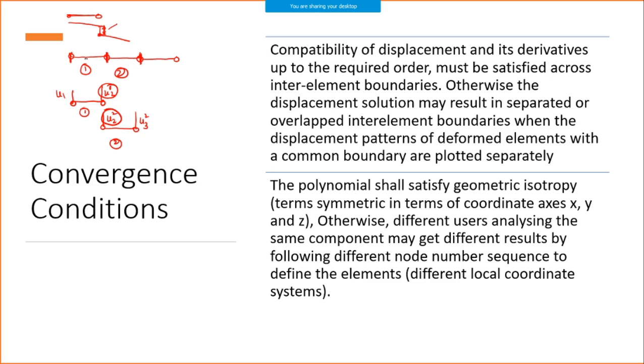we take care of uniform deformation in both elements. This and this will be the same, and that's what we add in these matrix equations, and we get a sum, where terms get added up, maybe at a diagonal location. So this is what is called compatibility.